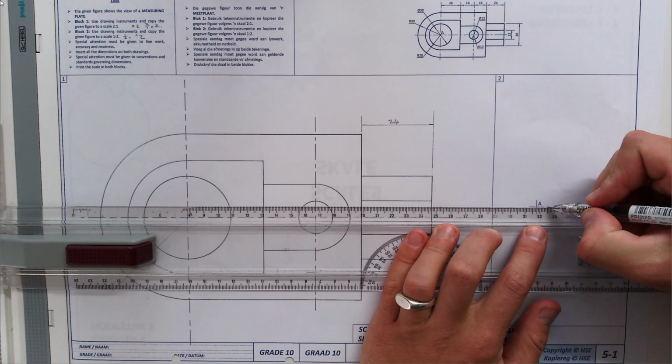Take your circle stencil. We are looking for a circle with a diameter of 15. Okay, so this is diameter 15. You can see here that on the circle stencil you have these center lines. You need to make sure that those lines line up with your center lines before you put that circle in. Okay, so there, mine is perfectly aligned on my center lines. Then you can put in that circle. There we go. That circle is in.